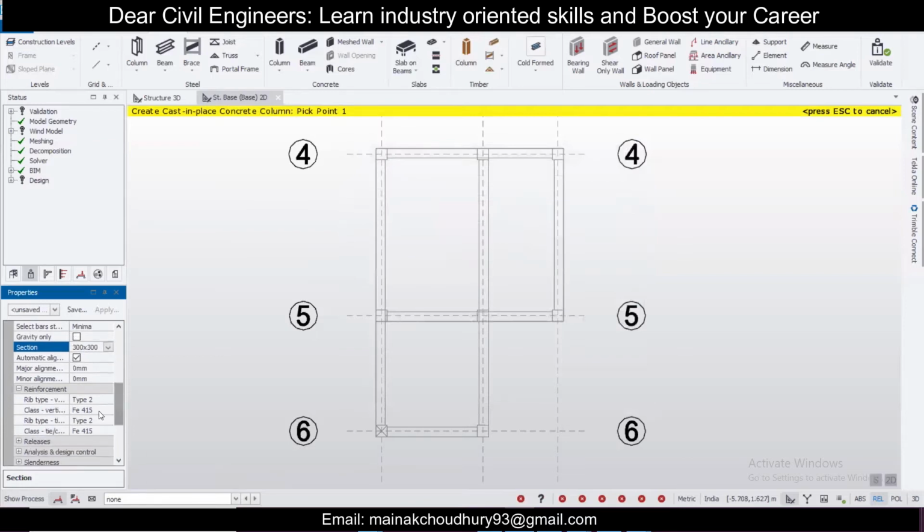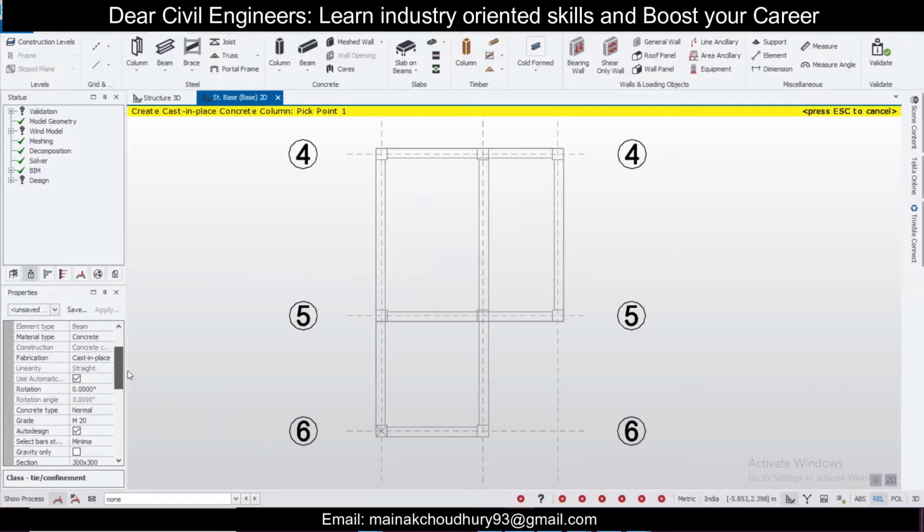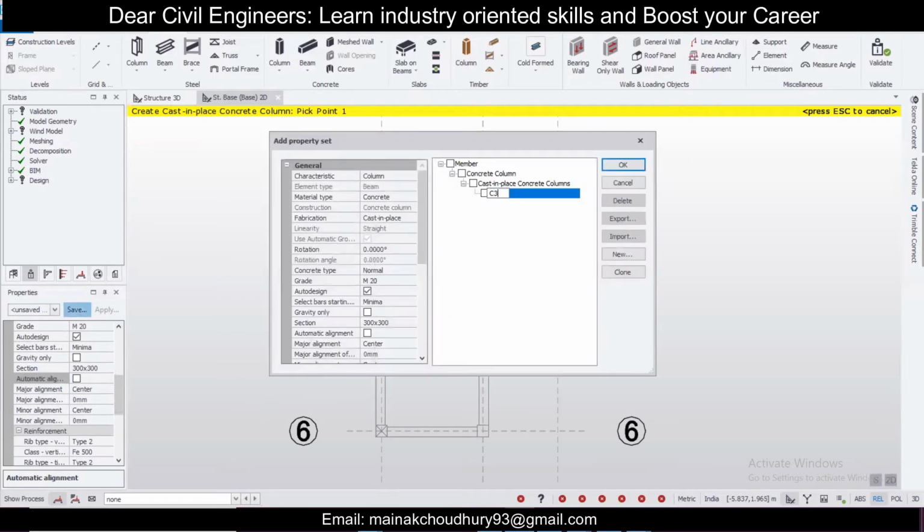So 300 by 300, and this Fe 500 is the grade of steel which we are providing. And let's provide the columns here. Now we provide here, it comes at one of the ends. So just press Ctrl plus Z, and first of all let us save this. Before saving it, untick this automatic alignment. Now it will be aligned to the center, and then just save this. We'll save this as C 300 cross 300 and click on OK.